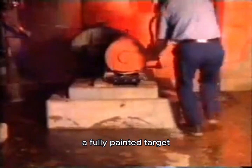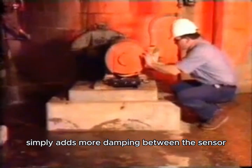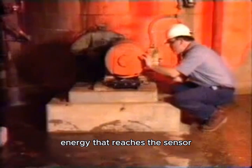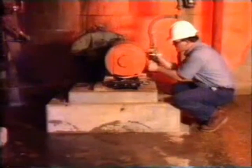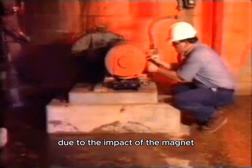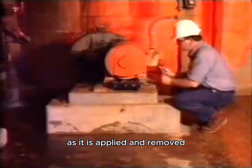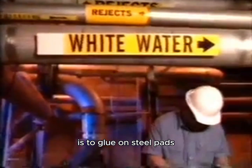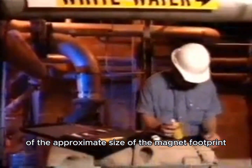A fully painted target simply adds more damping between the sensor and the source of the vibration and reduces the amount of energy that reaches the sensor. You will find that after several uses, the paint begins to chip off due to the impact of the magnet as it is applied and removed. Another common method of marking the points is to glue on steel pads of the approximate size of the magnet footprint.